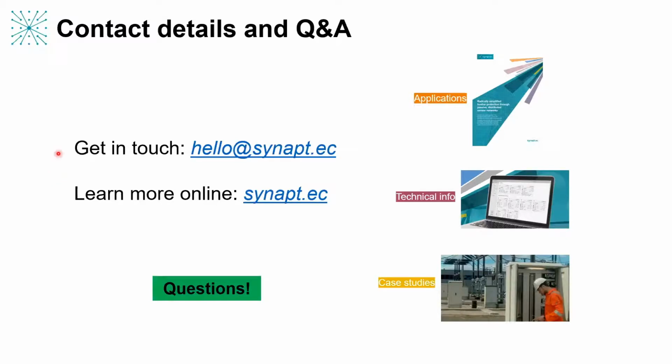Yep, of course. We design our system and test it against the standards required of the industry instrumentation standards, so that would be IEC 60044 or the new 61869, which requires us to sample each of our measurements and publish the measurement data within 2 milliseconds to be consumed by protection relays. And we comfortably meet that target. So even for the very distant sensors, where you have to factor in the time of flight of the analog measurement in the fiber, we're still very comfortably within that 2 millisecond horizon, effectively from sampling to output. So it's comparable with traditional measurement schemes in that way.